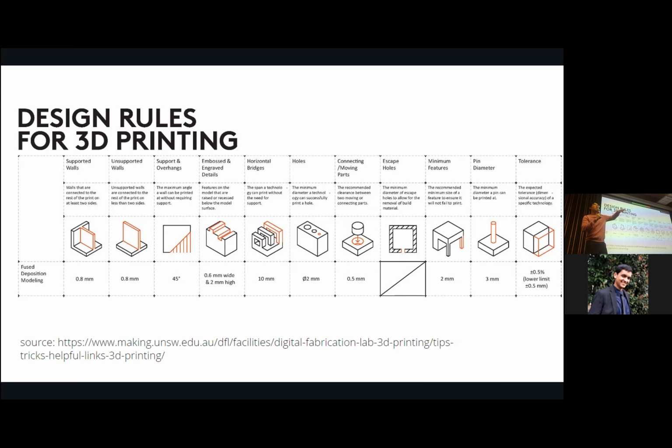So every layer builds up, it will build up more and more out. The usual rule of thumb is 45 degrees, but modern 3D printers can usually get away with 60 or even 75 degrees, which is what I got away with last time. At 75 degrees, it comes out pretty well, even at these high angles, if you have adequate cooling. This is determined by the material you printed and the temperature, and I will go through that in a bit.